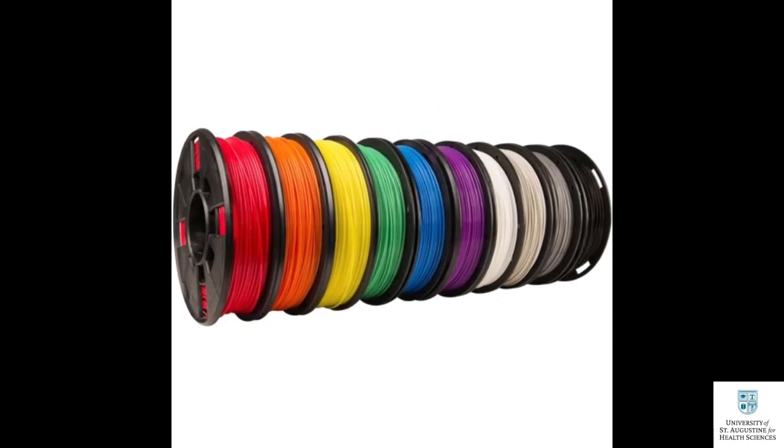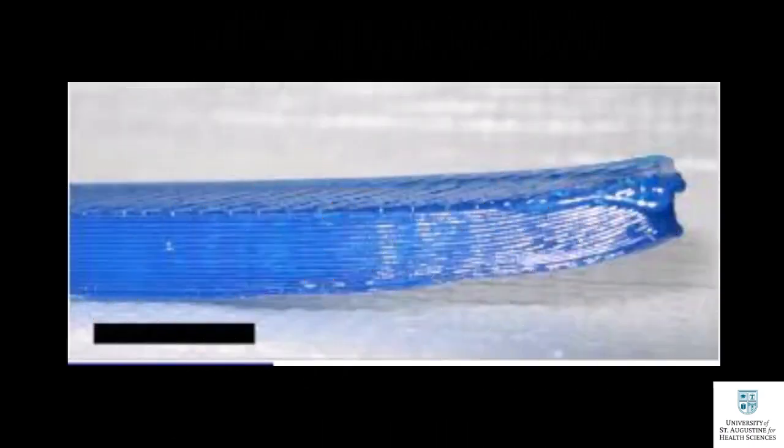flexible, and durable. It requires a print temperature between 356 degrees Fahrenheit and 446 degrees Fahrenheit. And lastly, it is not soluble in water. On the other hand, PLA filament tends to deform when exposed to a temperature of 140 degrees Fahrenheit or higher, and can become brittle after extensive use. Therefore, you should avoid using it to print devices that are prone to bending and twisting.